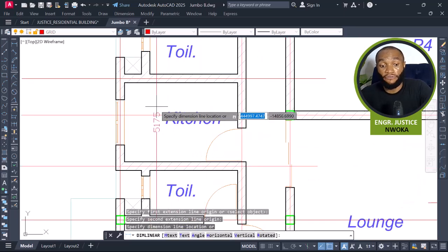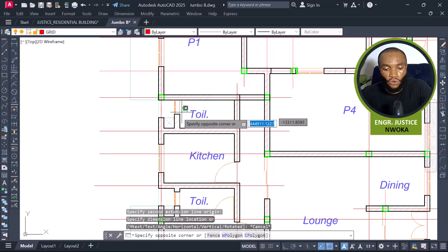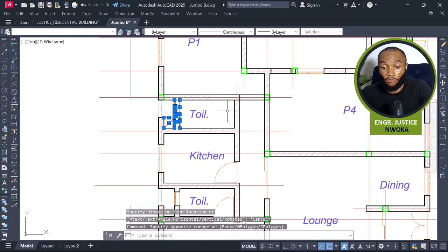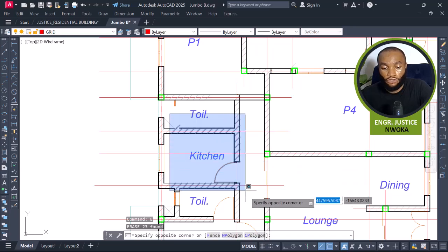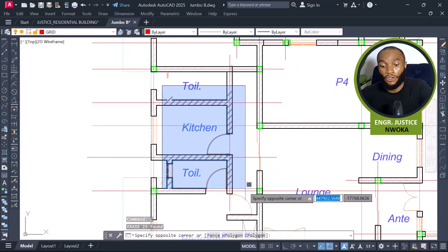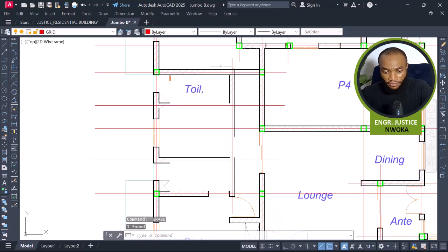So 4.5 times 5.175, that's less than 30. So with that, I'll eliminate all these block walls, which are meant to be used as a beam. I have saved cost than not using this stuff as a beam, but just as a block wall. So I have saved the cost in concrete. Okay, so I'll remove all this now, take all this off and take this off.